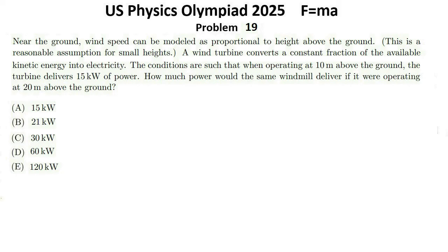Finally, because the speed is doubled, the power increases by a factor of 2 cubed, which is 8 times. That will be answer E. And that was the solution to problem 19.